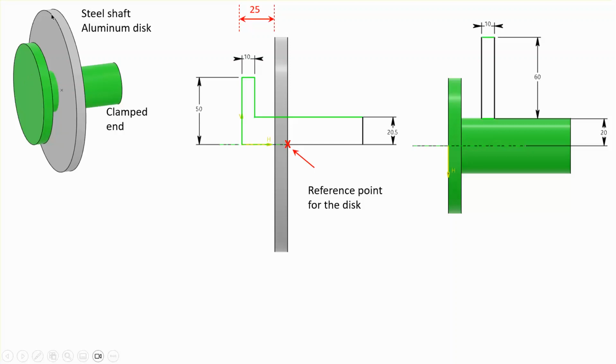So what people do is they heat up, for example, the disc, make it expand, so the radius becomes bigger than the radius of the shaft, and then they slide this thing in and let it cool down. That's really the whole concept behind this contact interference or press fit or pressure fit.